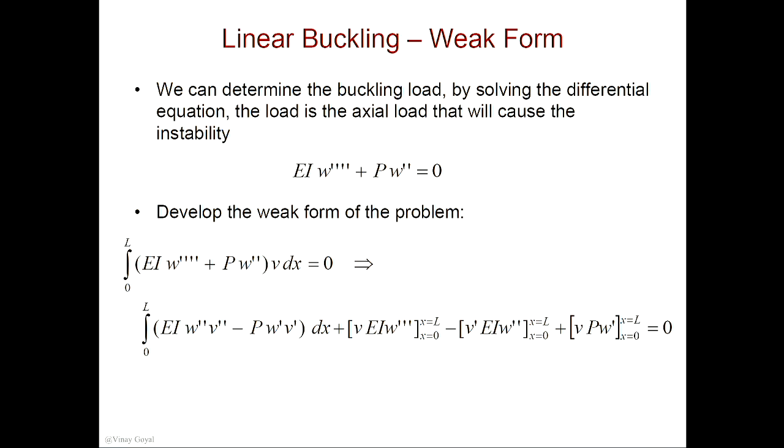If I wanted to do this with finite elements, the same problem that you learned in mechanics of materials, we can do that. We have the governing equation. I can multiply this by V to form the residual function. I can now integrate by parts. I did not show you how to do that because you know how to do this. And what I've done, I've split the order of differentiation on W here, and I've split the order of differentiation here as well. Two of them go with V, and then here one of them goes with V. And then I've just done the integration by parts here for you.